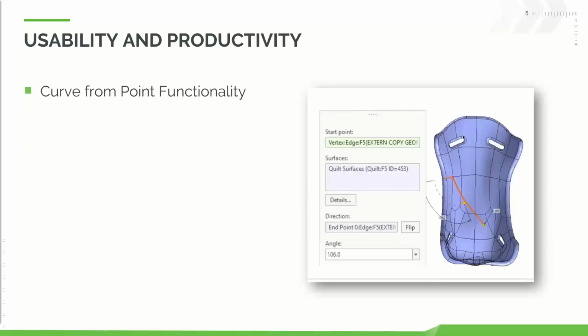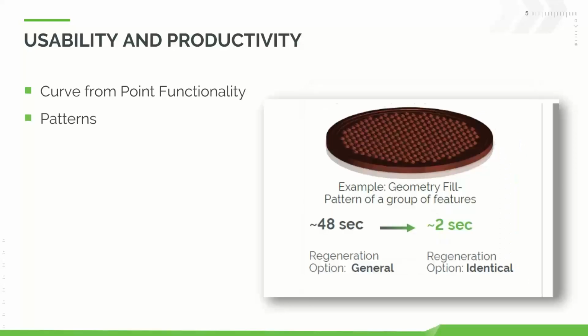We added in the ability for curve from point functions. Basically define a point, give it a direction, and now allows you to build a curve directly off of that. Really helpful for multiple different areas, surfacing, that type of workflow.